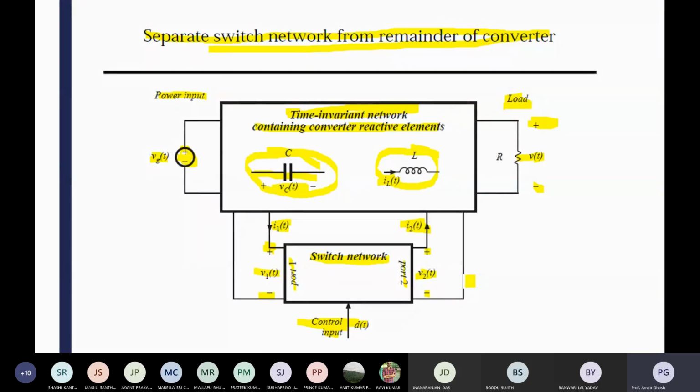Then you can use some switching combinations, so you can write some code, meaning switching logic. Logic is normally written in code form. So you calculate and process it through that path, and finally you get the output, the step response, or the Bode plot. That means time domain output and frequency domain output. And if you calculate the controller, you can do it in the M file too. All the differential equations should be written in the M file. That is process number one.